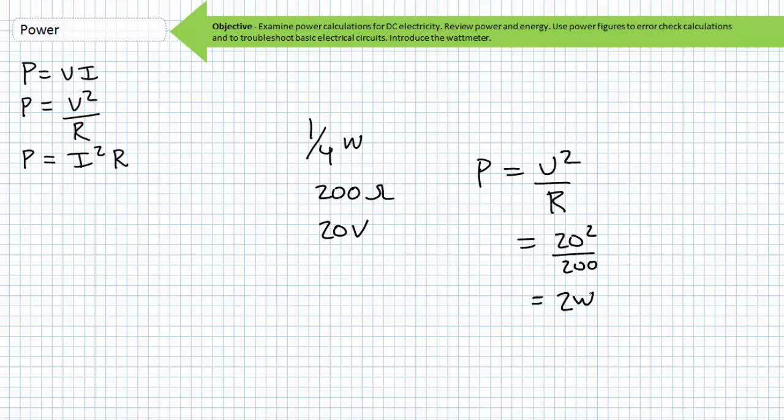However, is it wise to use a 2 watt resistor? Probably not. I think my car can maybe go like 120 miles per hour, but only in extenuating or really fun circumstances do I attempt this. Ordinarily, I drive it well inside its intended performance envelope. A general rule is to use components with power ratings twice that of anticipated conditions, so maybe a 4 watt resistor would be fine. Sometimes manufacturers specify power ratings even 4 times greater than that of anticipated conditions for systems requiring unusual robustness, like those operated in harsh environments or those with important safety considerations.